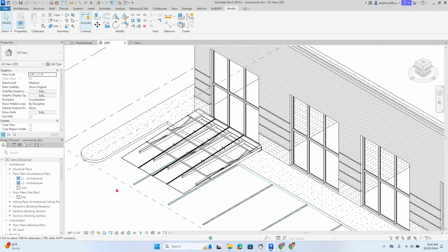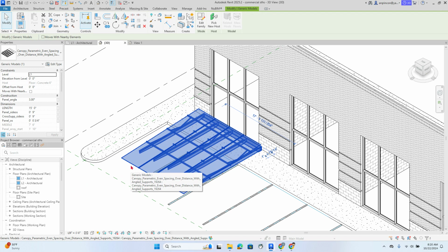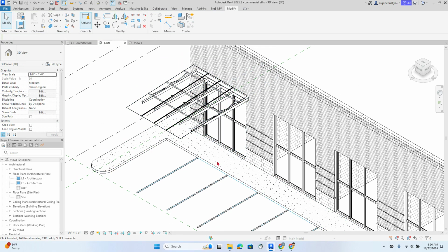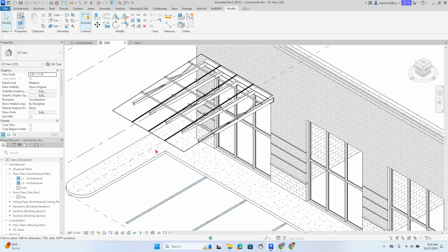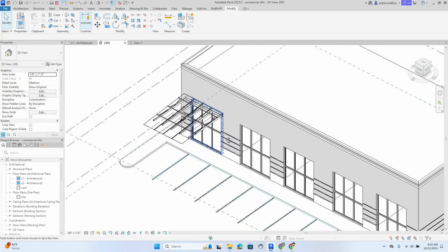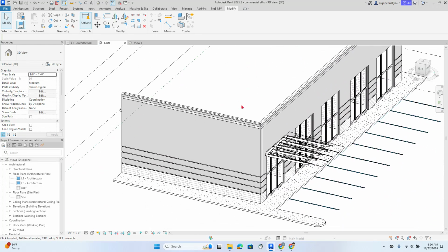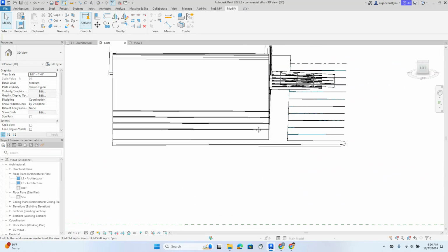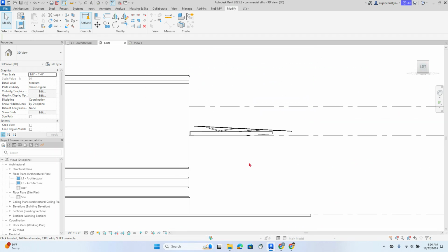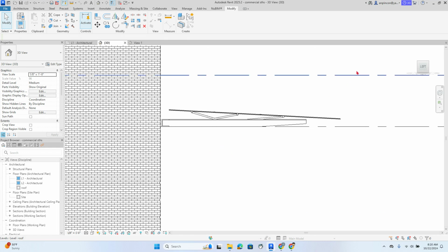Every component that you bring into Revit goes into level 0, right? Level 1 to 0. So what I'm going to do here is guesstimate my elevation to 16 feet up, so it's going to go 16 feet from the floor. And then if we analyze the elevations, for sure they don't look right. The canopy length is too much, right? The canopy length is too much. Okay, so we need to work with this canopy a little bit, right?